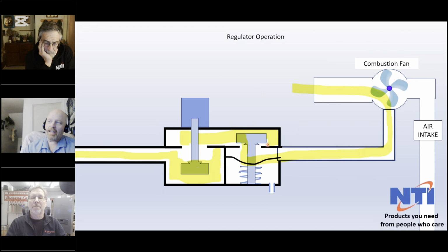Now, when we start to disassemble this valve, what you see inside here is there's the regulator plunger that we talked about at the bottom. The little spring is kind of hidden inside this cone. And of course, there's the diaphragm sitting on top of this assembly. And what I'm simulating here is I'm pushing down on the diaphragm with my finger, and you can see that the regulator is fully open. And on this side, the regulator is fully closed.